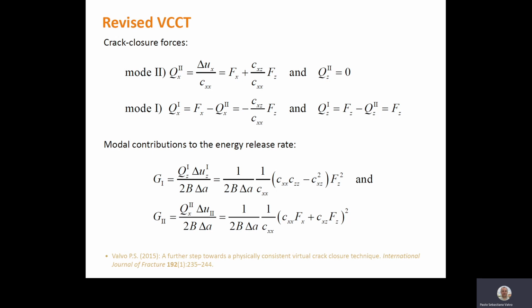Anyway, the modal contributions to the energy release rate can be calculated based on the expressions below, and it may be noted that contrary to the standard VCCT, with these revised formulations, G1 and G2 turn out to be positive definite quantities.